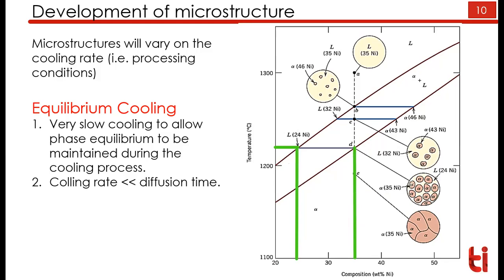So, and the microstructure is like this. When you reach point E, that is well below the solidus, like 1180 degrees Celsius, your liquid is completely changed into solid, and we have alpha. So at point E, the composition of solid is equal to the composition of alloy. So we have copper 35% nickel. So this way I can choose this alloy composition also.